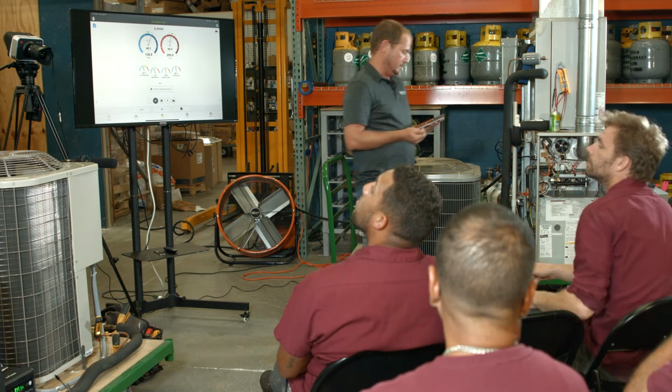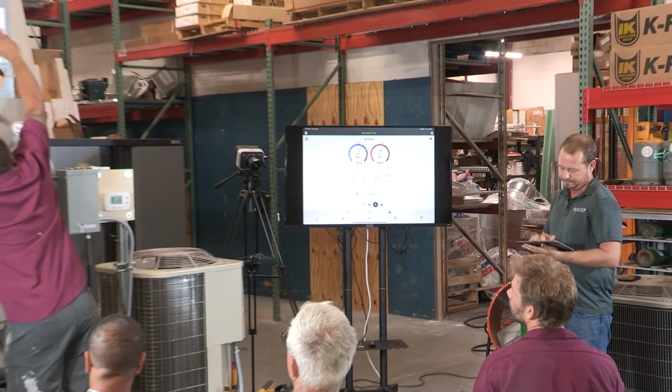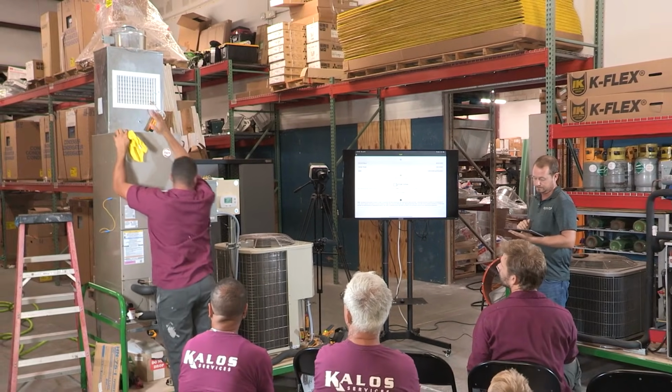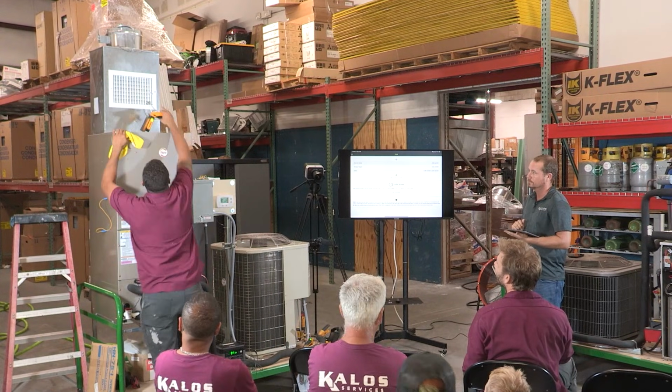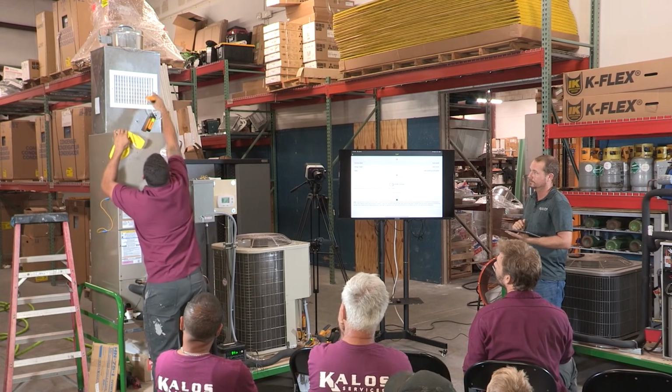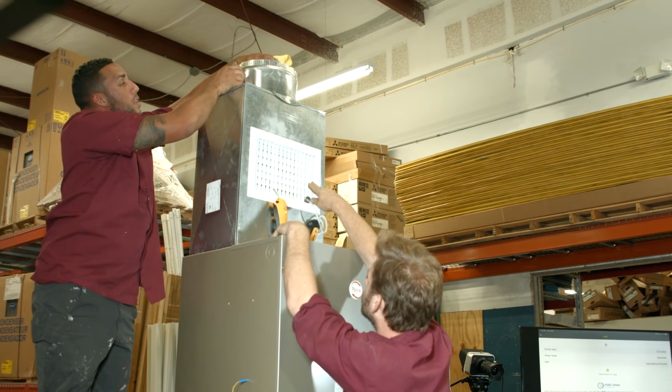Yep. All right, so let's go ahead and start by cranking down our supply airflow. Let's move it and get our static pressure. We'll watch our static pressure. Is that X13 in that unit, Brian? There's a damper on the top too. We're gonna keep that one open. Yeah, the damper on top, that's going to stay open. We're going to watch our static pressure.